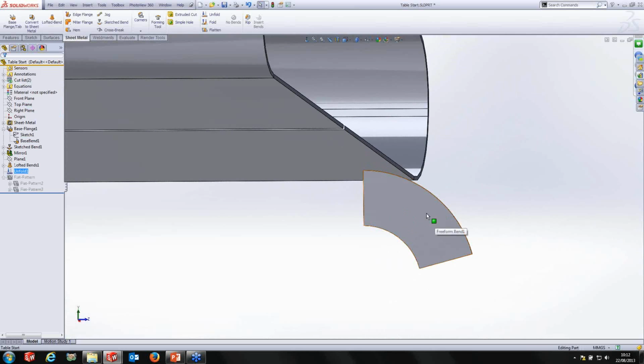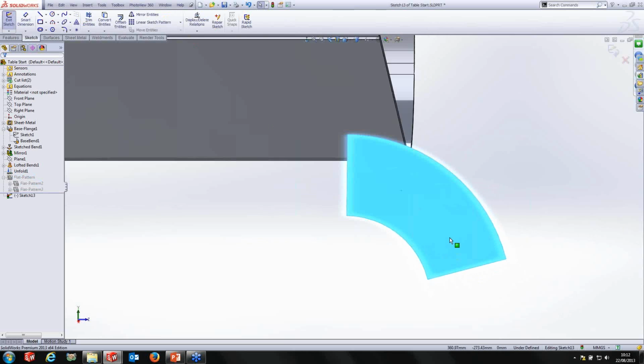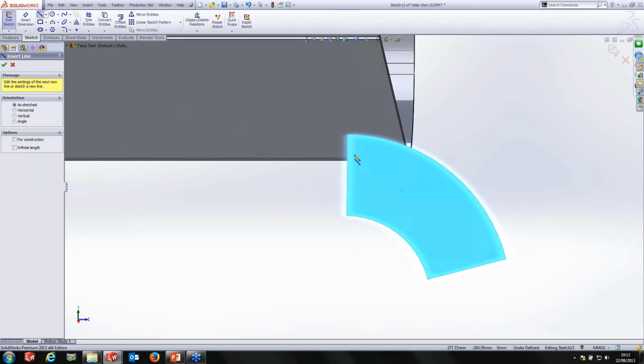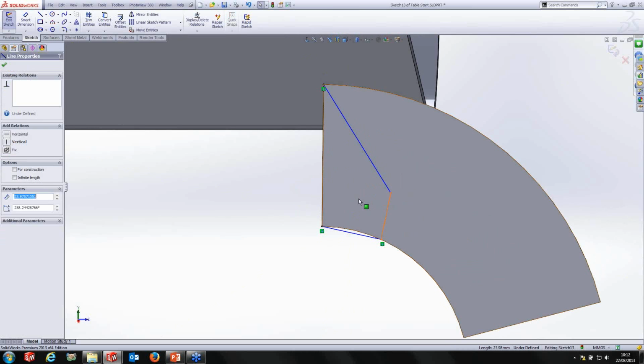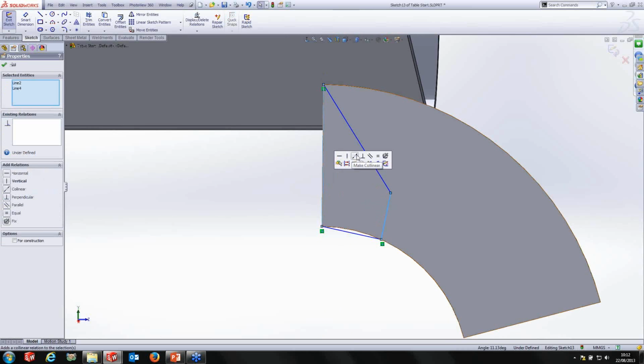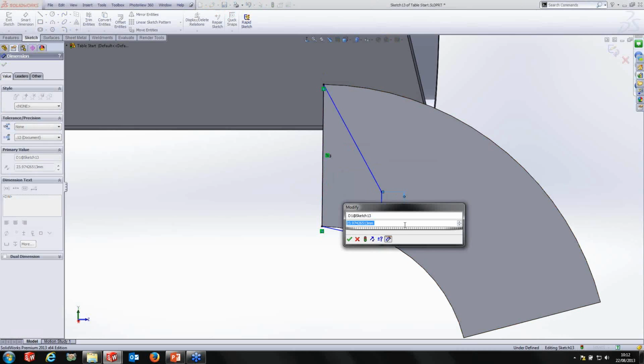So in this particular flat form now, you see we've unfolded it. We can then go ahead and create our sketch on this face because it's now completely flat. Okay. So just create a very quick sketch on there. I'm going to make sure these two lines are parallel to one another. And I'm going to put in a few dimensions just to control the approximate size.